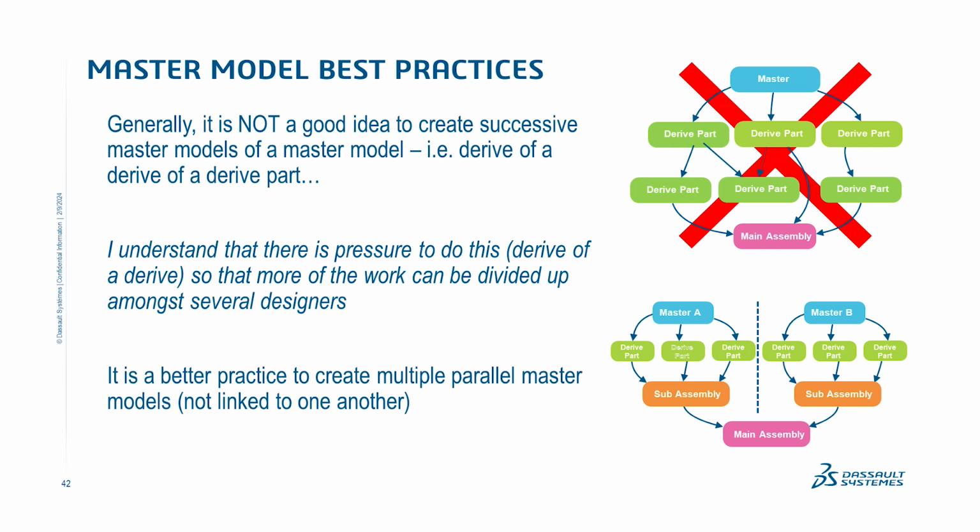So what I recommend to groups, instead of doing this, is to do parallel masters. For instance, if it's a robotic arm and there's a very simple circular reference between different actuator joints, use that circular joint or that sketch or that diameter and create the different actuators as their own master, deriving parts from those.